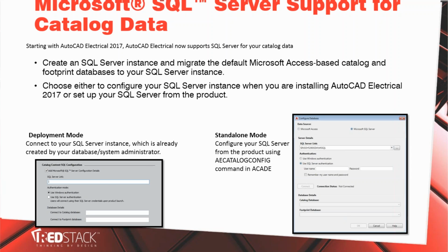The other option is like a one-person or smaller environment where the SQL is stored on the local user computer. So it's the same computer I use for AutoCAD Electrical. And you can also create an SQL on your own computer and use it that way as well. The SQL supports the free Express SQL and also the full version SQL as well. The difference is the full SQL gives you unlimited, where the free Express gives you a 10 gig limited database.